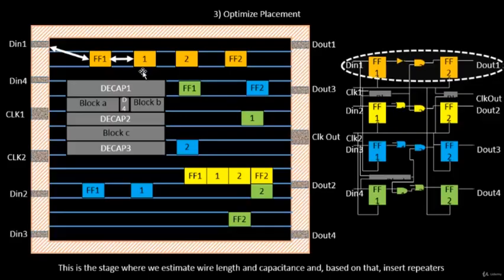We'll be talking about transition analysis and data slew analysis. The slew is dependent upon the value of the capacitor. The higher the value of the capacitor, the more charge is required to charge it, and the slew will be even worse. Based on that, we estimate whether the signal will be reproduced correctly in the receiver stage.